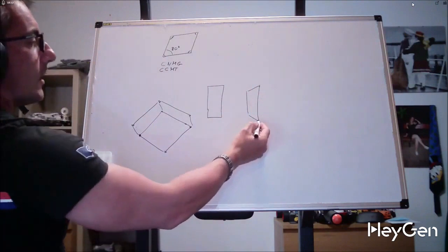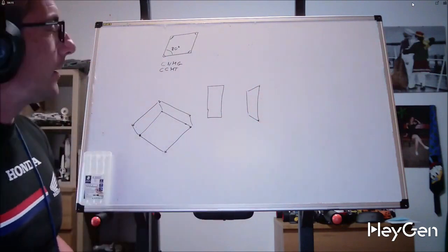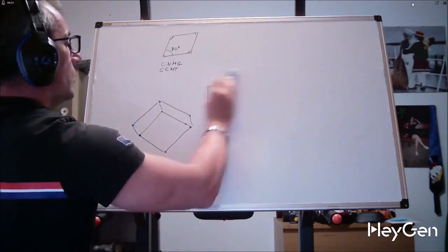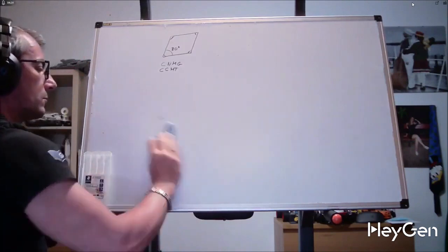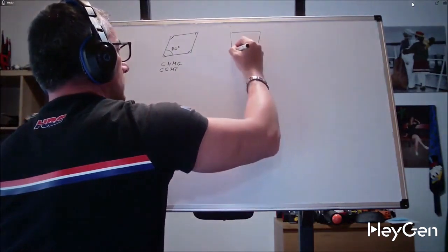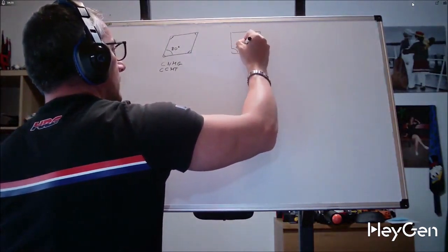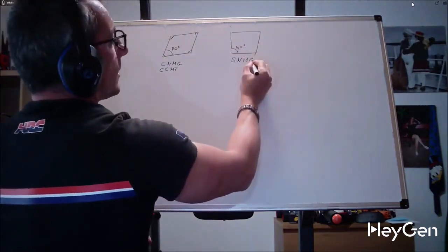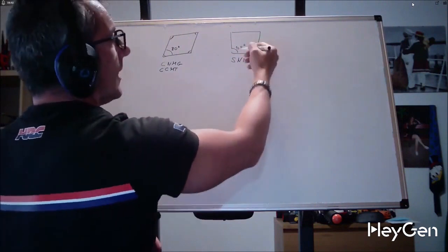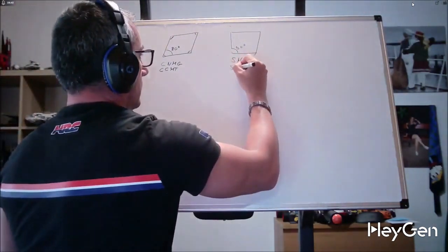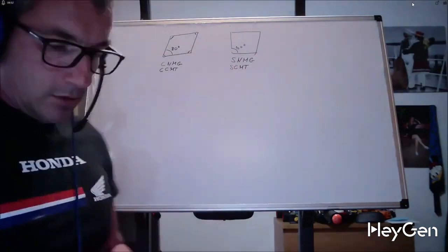So let's look at them briefly. I have an example with me and I will show it to you. First I will draw the square, so 4 corners at 90 degrees. SNMG sometimes also changes this last letter to SNMA, which means it is flat, without a chip breaker, for cast iron, or SCMT. Here I have an example of SNMG. Let's try not to mess up with the camera. SNMG is this one and SCMT, okay?